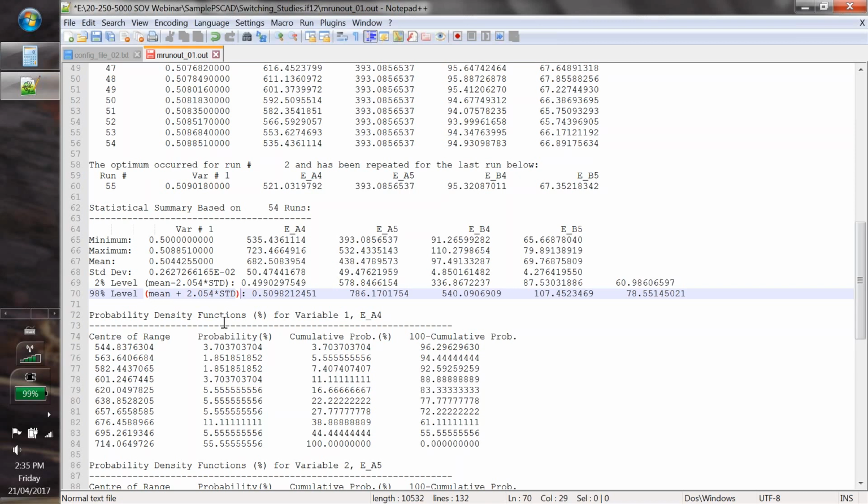The next question was, how about saturation of shunt reactor? Should they be modeled as saturable reactors? If you do have data for them, you can represent them as a saturable reactor. If not, you can model them as a simple reactor.